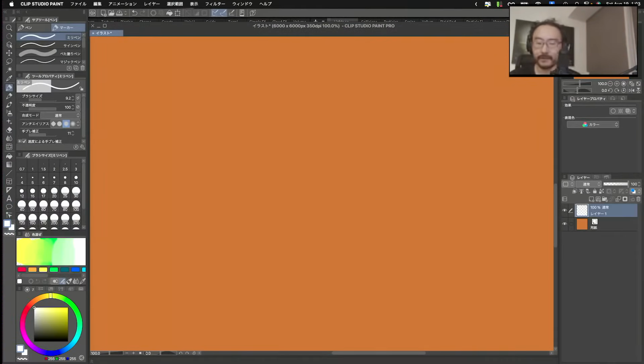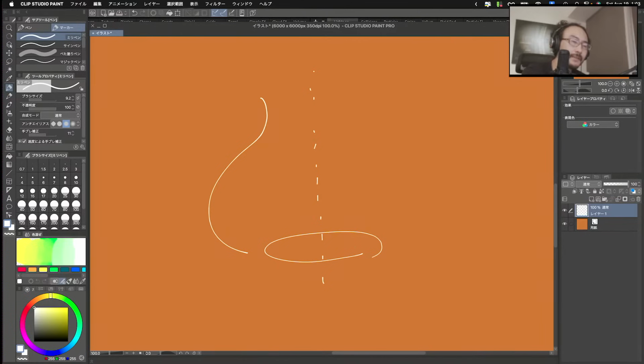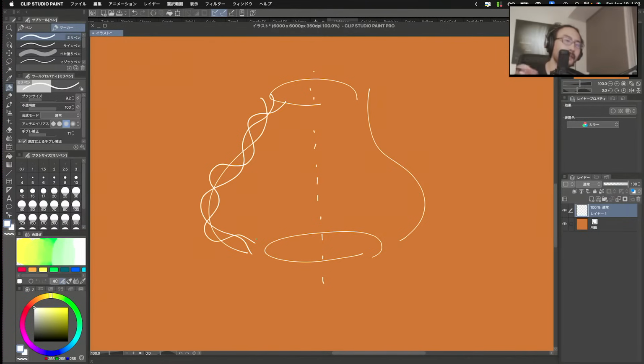Okay, so this is what I'm gonna do, and since the logic itself is pretty easy, I think it's nothing difficult for today. So the process that I'm gonna do today is to first set up some profile curve for a cross section in order to create a vessel-like shape using revolve. And I'm gonna create a bunch of profiles by creating a wavy shape based on the input curve. And for each weaved or wavy curve, I'm going to create a different profile and different revolved geometry.